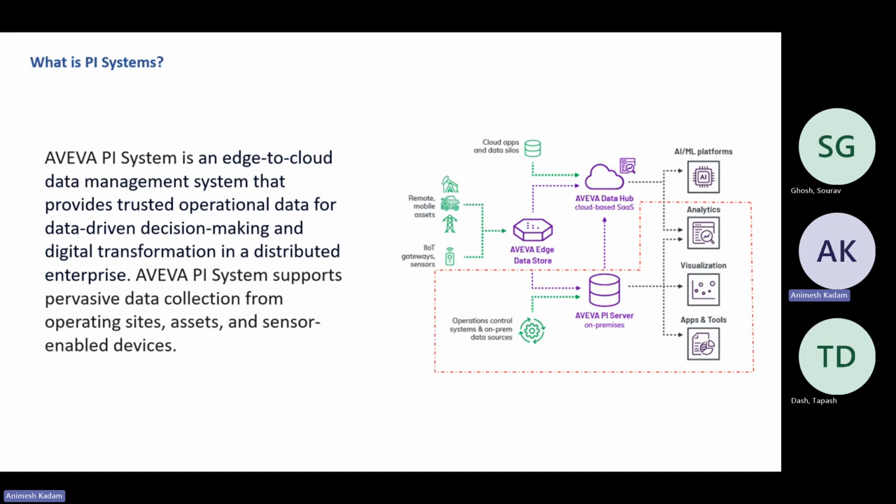You know what a data historian is, right? It is only to collect and store data from all sorts of assets, basically the OPCs, DCS, PLCs, and a few databases. Pi started as a data historian, and then it evolved over time into what we call a data infrastructure today.